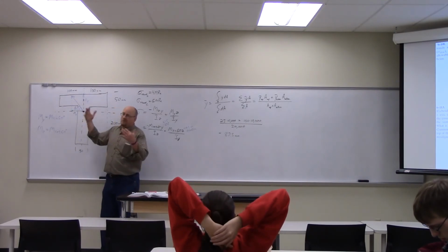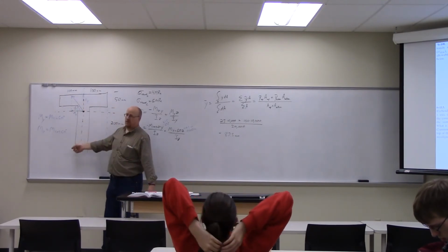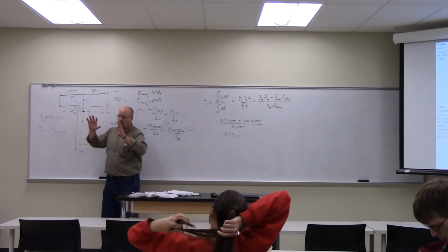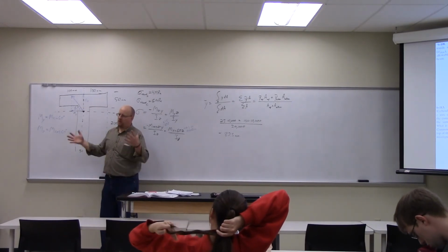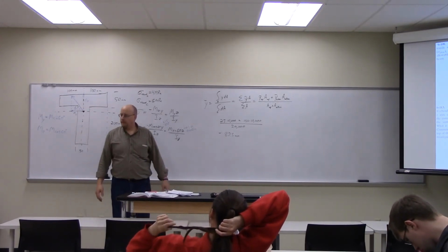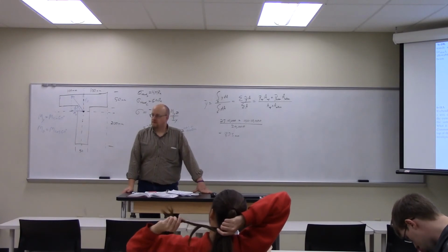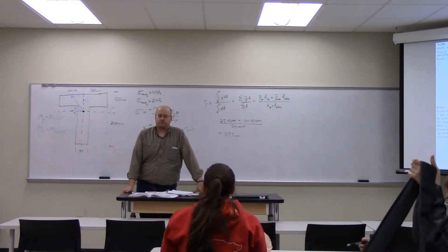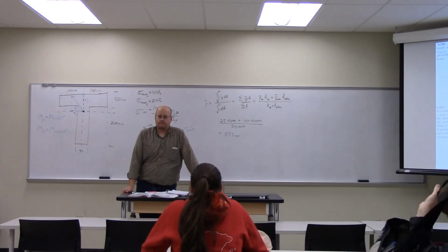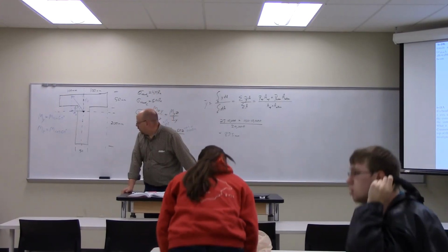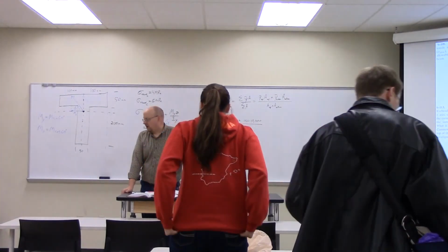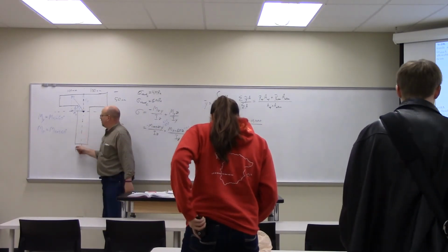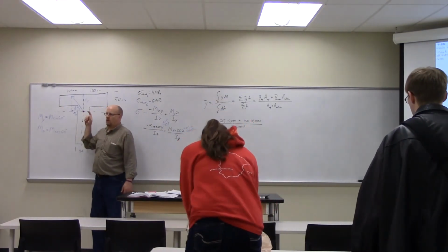But when you can tell that this is going to be the danger corner, you don't have to worry about it. It's just if it's really close together and you can't really tell for sure, then you go in and try it. But there's not a neutral axis that can go through that centroid. The bottom line is not going to be further away. The distance from here to here is greater than the distance from here to here.